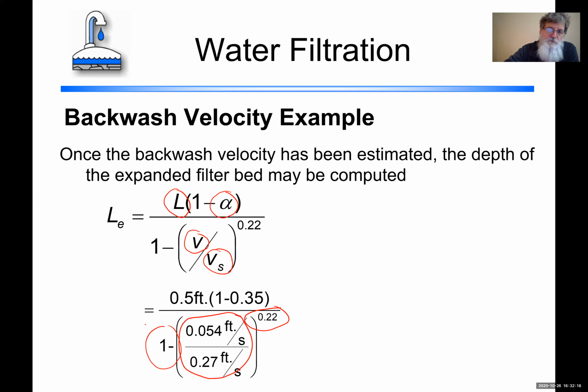Okay, hopefully you're back on and you have a number. Let's compare your number to mine. I got 1.09 feet. So that means the bed, which was originally about 6 inches deep, in backwash expanded basically double the size, to a little over a foot.